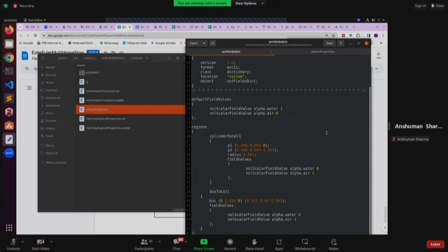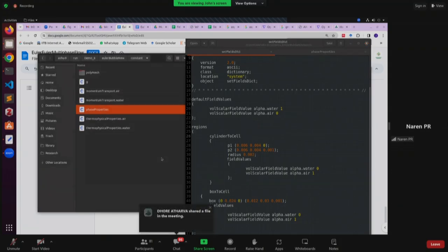In this case, what Mr. John has shown is that he has just taken water and an air bubble. The air bubble changes its shape, though not in the Eulerian context. Physically, imagine a bubble or a collection of bubbles that change their shape and size. The pressure inside the bubble is changing, and there is a pressure drop happening. All of that is there, but still we are saying density is fixed. We are imposing that it is an incompressible system because we are not talking about very high speeds.